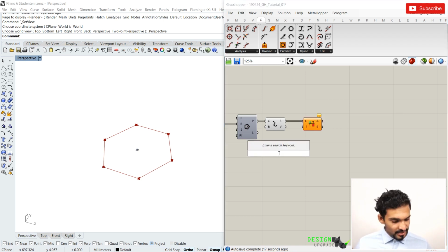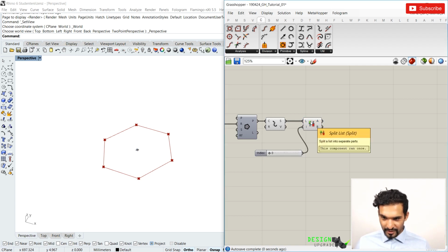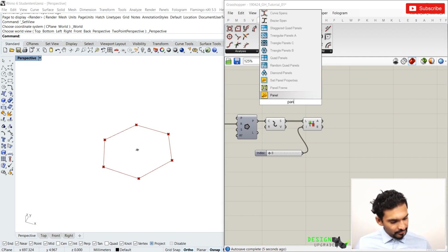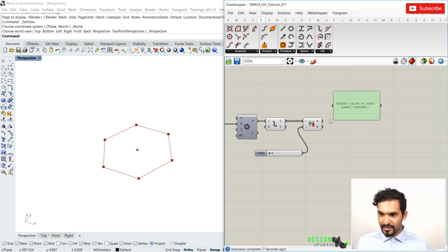So we can test that, just get another slider, 0 smaller than 5. That's the range that we have, right? So it starts with 0, 1, 2, 3, 4, 5, 6 numbers. We get this guy here, hook it up, and then we can put a panel. Now we can just type in panel. And if you just hook it up to A, you can see that currently we have nothing. And then if I scroll up, you can see now it actually has 1 line in it. And then as we go along at 4, we actually have the first 4 lines filtered.